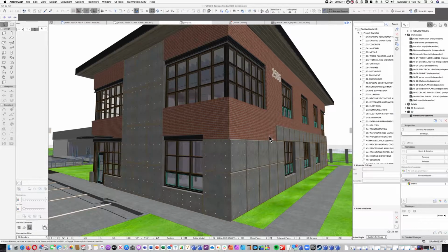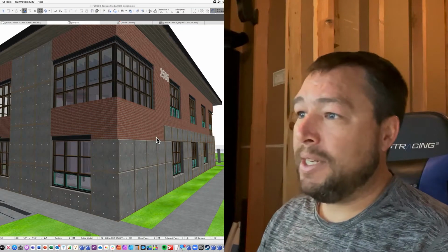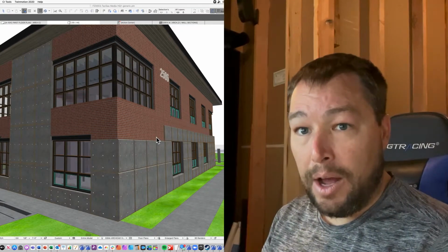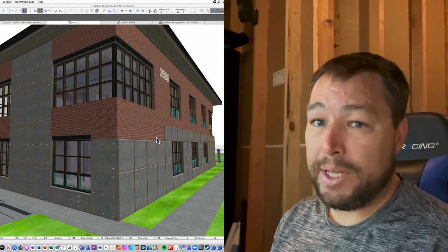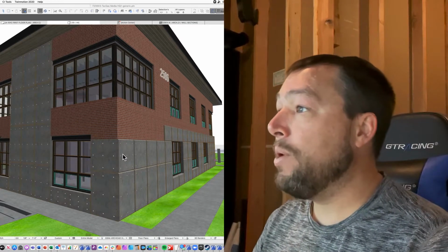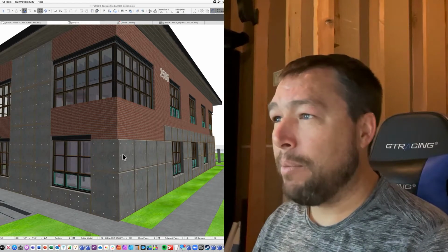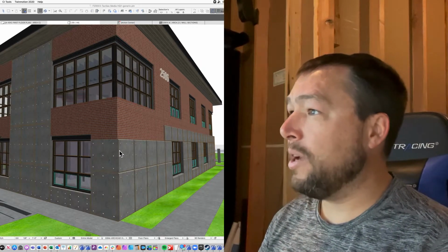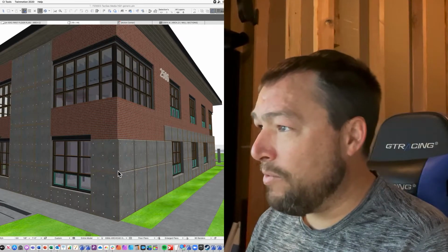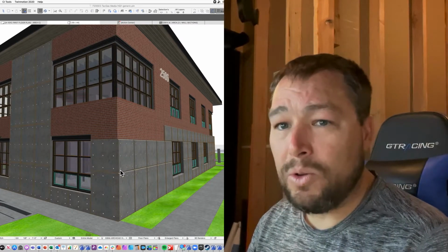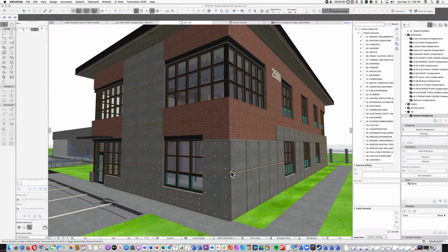Okay, again, today we're going to be talking about exterior claddings. So here's an example of a recent building that I did where I wanted to define where the control joints are, the panel joints are in the concrete. We went with a kind of a brutalist style concrete mix, where we've got the reveals and the tie holes actually exposed. It was part of the idea of creating a fortress-like feel to this building.